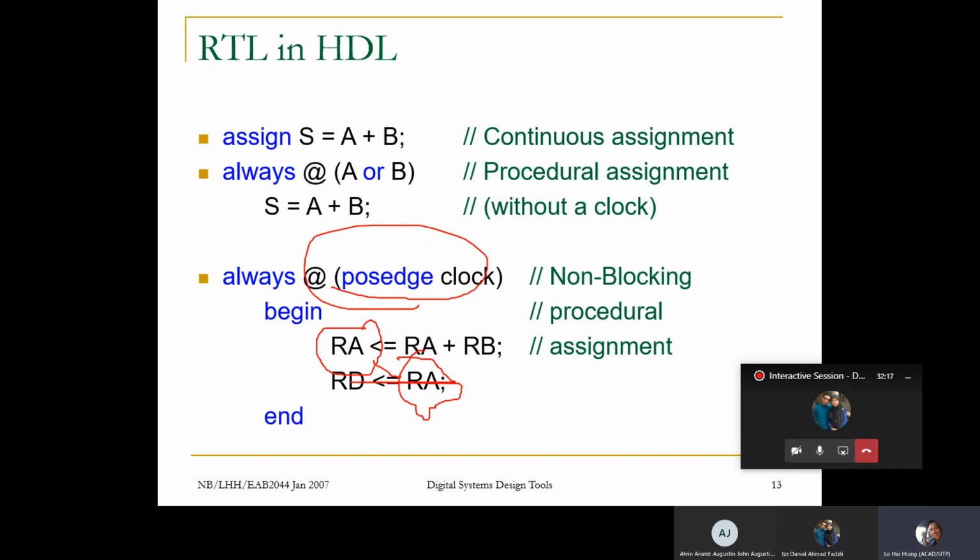You may want to write this down: because of the non-blocking features of Verilog, the netlist, your program, actually we shouldn't call it a program, it is the netlist we generate, may behave in ways that you do not anticipate, because we are so used to the normal software programming paradigm that we expect the assignment to happen immediately after the operations. This is not the case. It doesn't happen immediately. You have to wait for all of them to be evaluated on the right hand side.